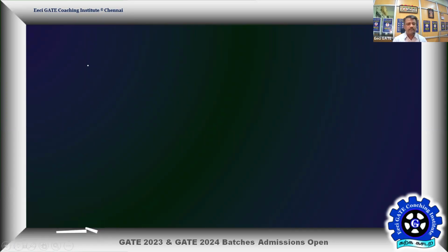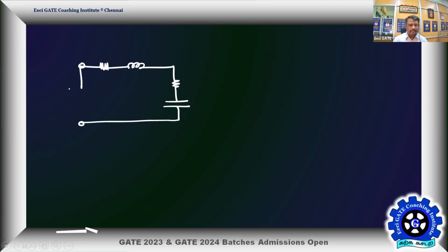The given circuit is, I have the resistance, I have the inductance, then I have the resistance and the capacitance. So that's a new RLC circuit, again excited by the same frequency omega. So this is a coil, it's having R1, and this is omega L, and this is having R2, this is having reactance 1 by omega C. Okay. So this is j and this is minus j.